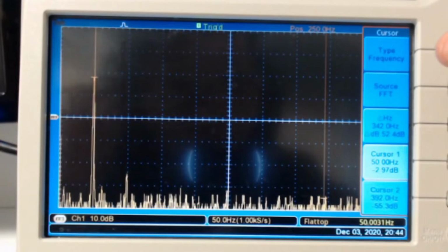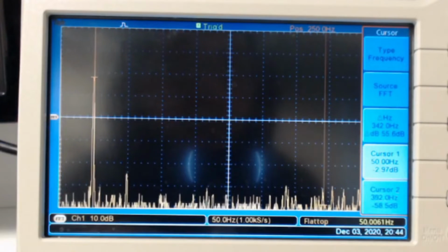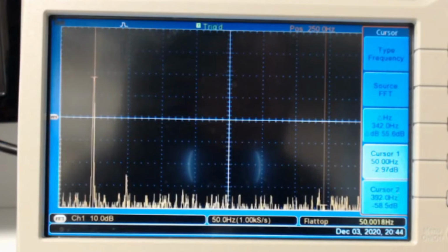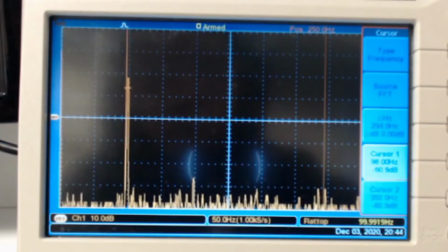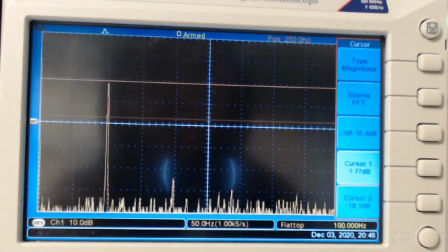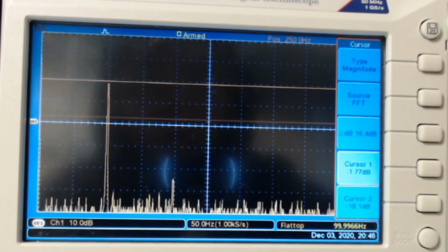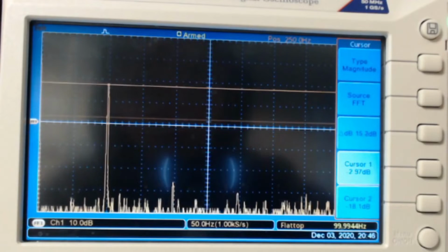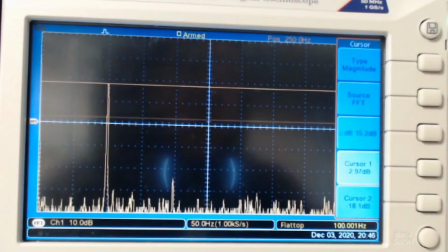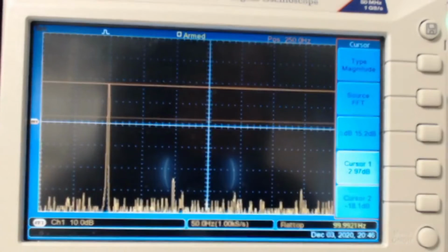At 50 Hz also still minus 2.97, previously also minus 2.97. Now I will change to 100 Hz. While I'm doing it, the frequency cursor is not moving well, so I will just use the magnitude cursor. Here I just go to the top, the peak, still minus 2.9 at 100 Hz. Let me jump to 300 Hz.